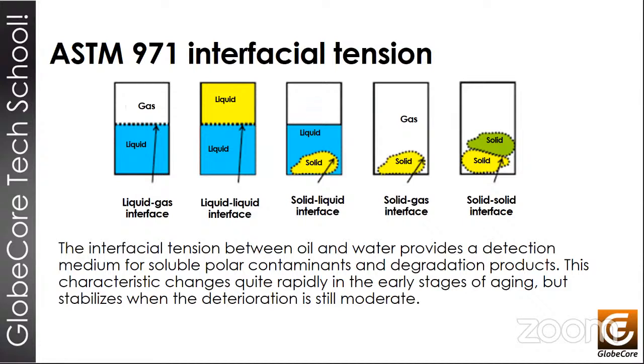Because when we see these things start to go out of limits, that's a good sign of premature aging of the oil, and therefore the aging of the transformer. Now, when we see that, the first thing we have to do is to get rid of the material, substance, or problem that causes this premature aging, and then we can regenerate the oil. Okay, next slide, please.